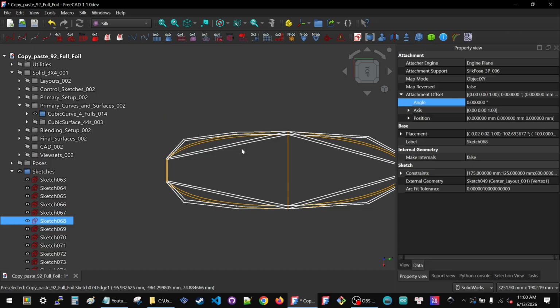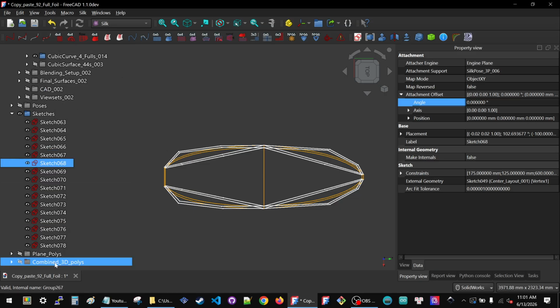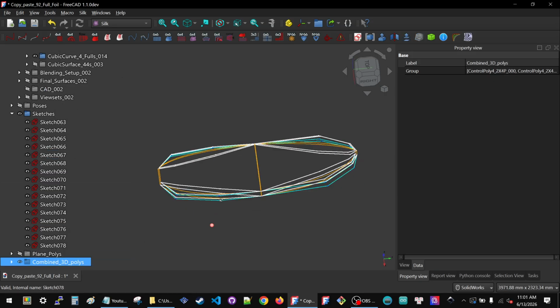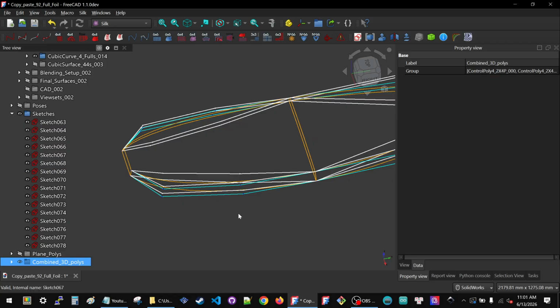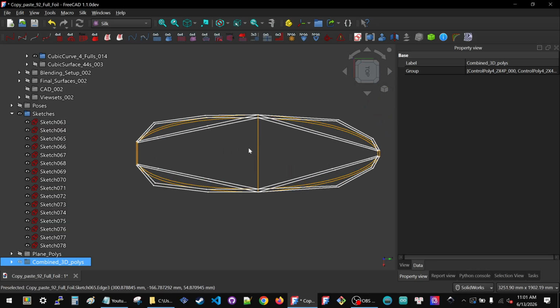And the whole point of all this, and I'm not using a mixed curve, like I think if you want to combine two curves with as many control points as you want in either of them and not have to make any of these sacrifices, Curves Workbench can hook you up. But in Silk, we really, really want to keep these combined 3D polygons to be 4 points, and so we spend time setting up the different planes to get the shape we want in both directions.